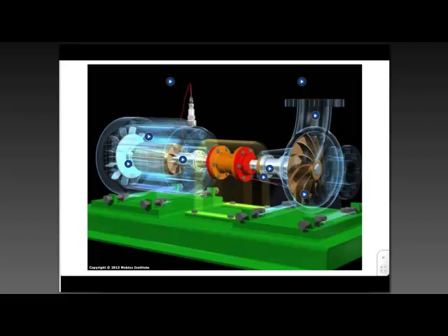So in this instance, we are interested in the rolling elements themselves, the health of the rotor itself and the windings in the stator and the rotor. We're interested in the coupling and the vanes in the pump, to make sure we don't have cavitation, and certainly the bearings on either side.